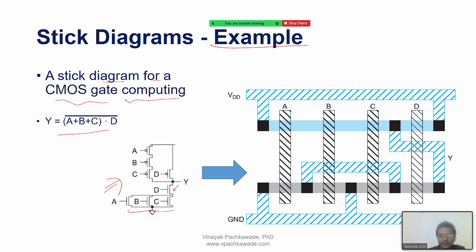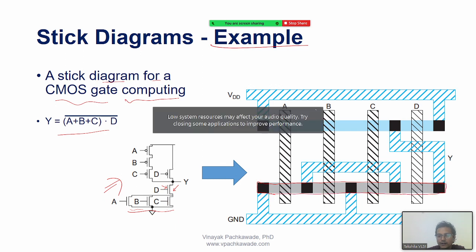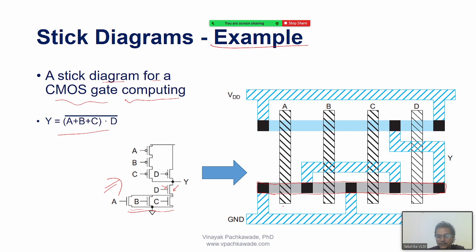I could have drawn the 3 parallel combination just like before, and then somewhere placed another transistor to make the series connection of it. But what I did is that the layout is in such a way that this is NMOS, 4 NMOS, and how are they? This is 1, 2, 3 and 4, because poly helps me to understand their division, sources and drains.